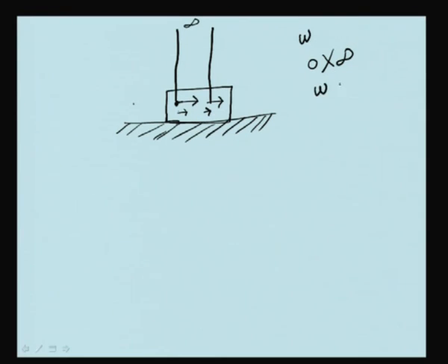Actually, the velocity is omega into r. If you say omega is equal to v by r, into r, as r tends to infinity, this tends to finite velocity v. So, 0 into infinity can be considered as 1 also, it can be considered 2 also, like that. Thus, the translating body may have any velocity with 0 angular velocity and instantaneous center at infinity.